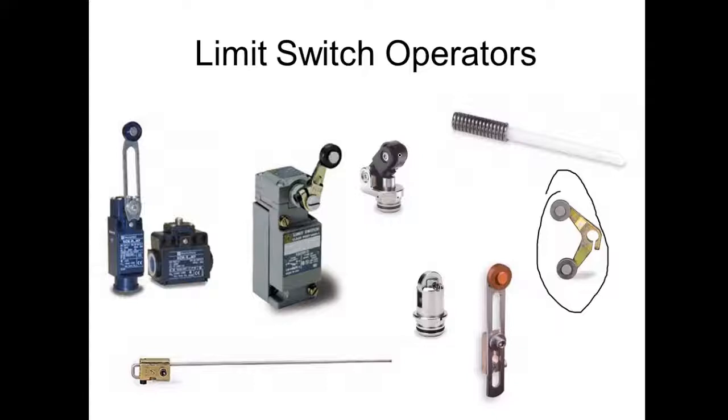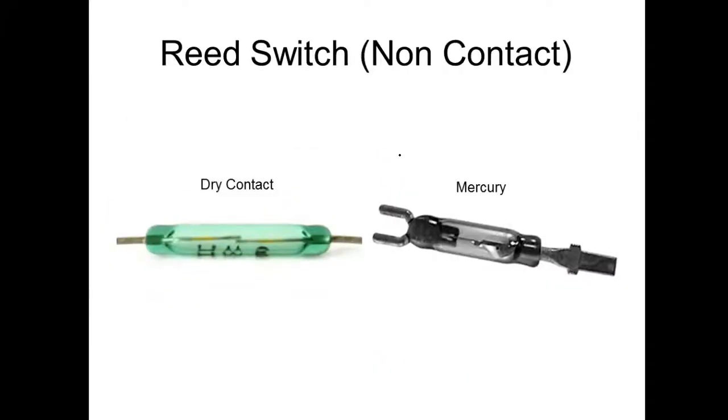Okay, that makes sense. So a limit switch is a proximity switch, but they don't usually put it in that category because it's been around so long and has its own name. So normally when we talk about a proximity switch, we're talking about a non-contact sensor that tells us when something's at a certain location. And of course, we have what we call magnetic reed switches.